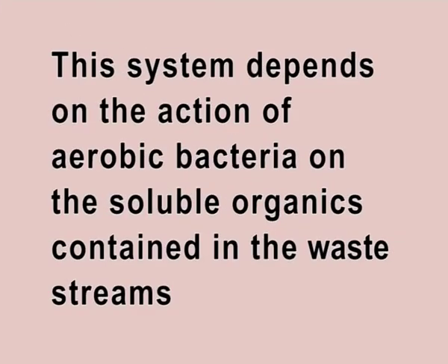A common practice for improving the effluent treated in the aerated lagoon is the use of stabilization or polishing pond system. This system depends on the action of aerobic bacteria on the soluble organics contained in the waste streams. The organic carbon is converted to carbon dioxide and bacterial cells.